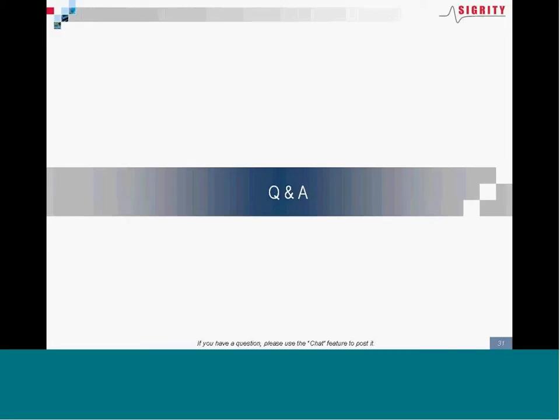One thing you can do in the tool that helps quite a bit is you saw how you can look at the modified impulse response for those models that use the AMI init technique, and you can even look at the raw waveforms pretty easily to see the before and after for those models that use GetWave. So there are a number of debugging techniques that you can use with the tool to help test out the functionality of those models, and we've used those extensively with the SerDes IP suppliers that we've worked with.